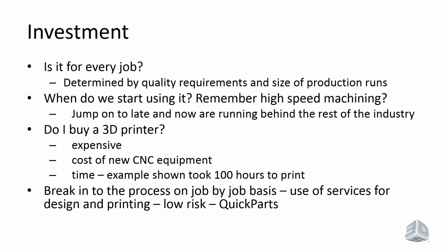The production volumes are such that you're not going to see, down at the end, a return of that money. And it may be that the quality is something that's not so big a concern. However, if the part does have major quality concerns involving warpage, or if there is a significant reduction of the overall cooling time such that it does reduce the overall cycle on a big production run, you may be throwing money away by not doing it. So it's a decision to be made based upon the job or upon what the customer dictates is necessary for the quality of the part.